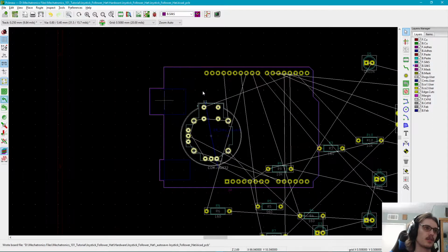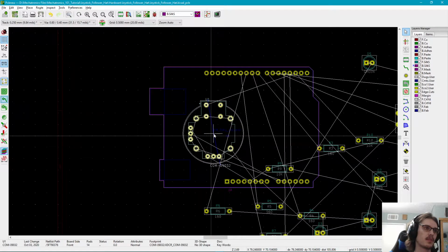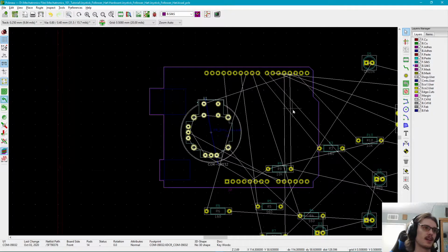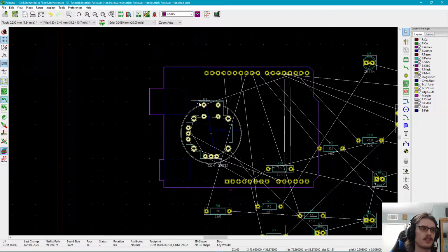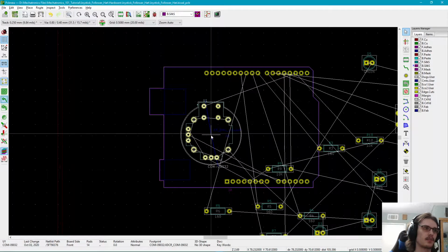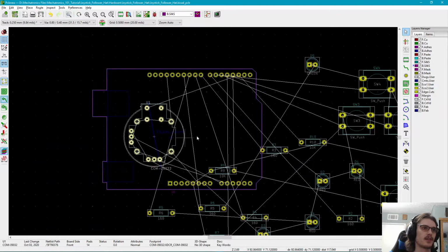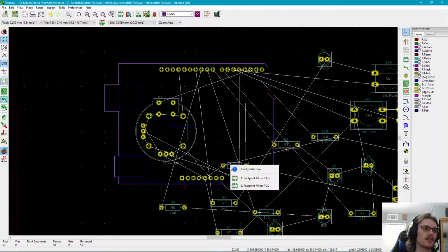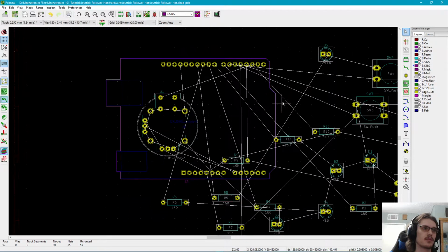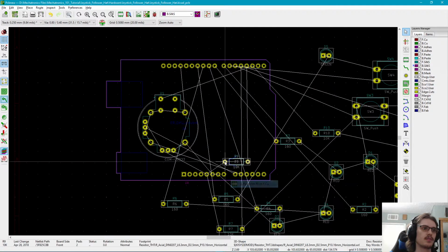So the joystick, we know we want it to be on the left, and it's a good point to start because it's pretty big and a lot of things interact with it. So starting here and building around it would probably be a better point. So what we're going to do is sit it in here because there's enough clearance for it, and we want to get it as far left as possible because it'll give us more room for the buttons. Okay, then after we have placed that, I think next would be appropriate to do the buttons.